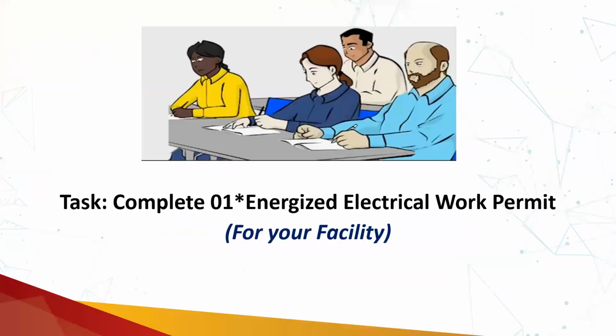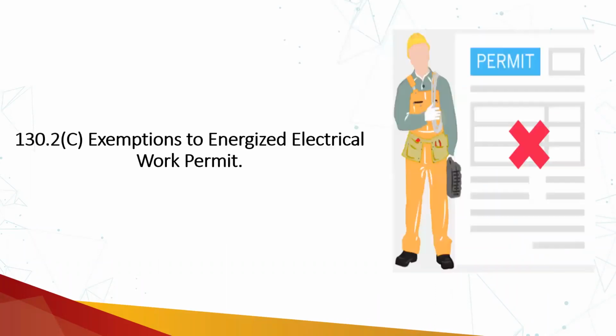So just try to complete some energized electric work permit for your facility to determine whether the tasks which are being performed on the live are justified or not. Any questions up till now? All good. So 130.26 talks about the exemptions for energized electric work permit.